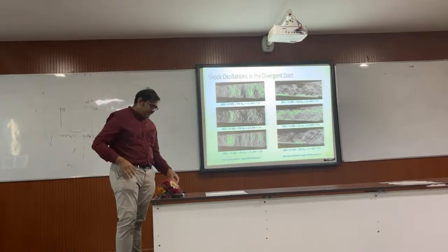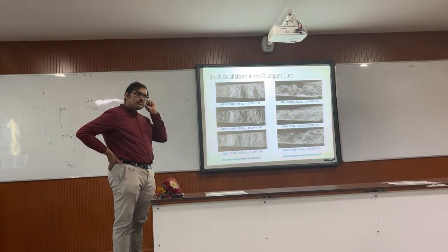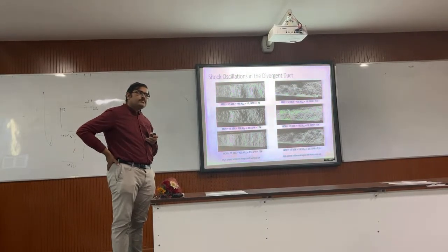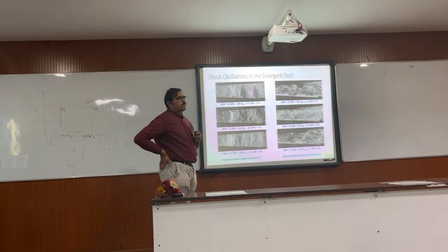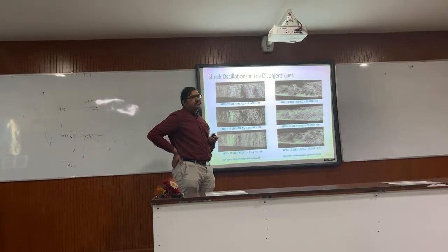This question is about the ratio of specific heats, gamma. We are conducting tests at a laboratory at ground level, while supersonic scramjets can be released at various altitudes. Is there any scaling or sensitivity we need to consider? The composition of air is more or less constant. For the scramjets we are looking at, the altitudes are something like 30 to 35 kilometers, so there the composition of air is not changing much.